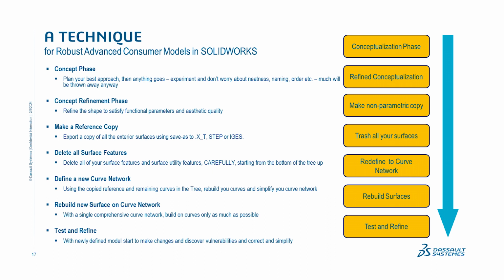But before you do any of that, I want you to save a copy of your conceptual model and a copy of your curves. I'll talk more about that. And then the really important step and kind of the game changer here is I want you to rebuild your curves as a curve network, meaning that instead of creating curves on surfaces, creating another curve on another surface, and so on, I would want you to create as complete as possible a network of curves that defines your design intent of your model.